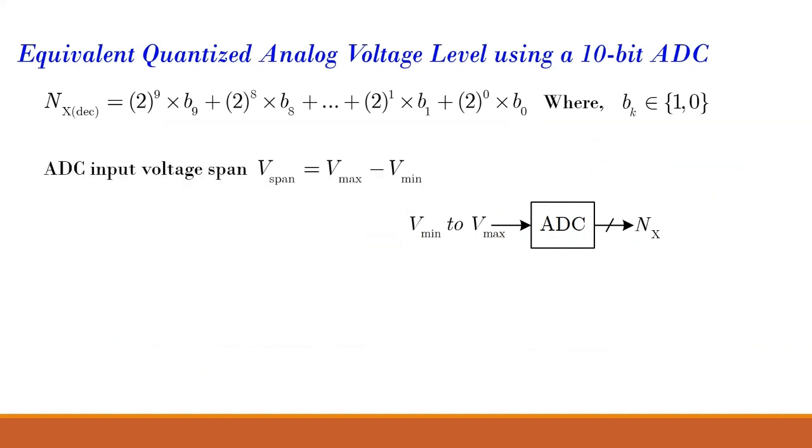Okay, wait. Let me just see over here. This is my ADC, right? This is connected to 3 volts. This is connected to my ground. If I apply 0.1 volt, suppose this was a 3-bit ADC. Okay, let us assume a 10-bit ADC. So the resolution of the ADC is 3 by 2 raised to 10, that is approximately 3 millivolts.